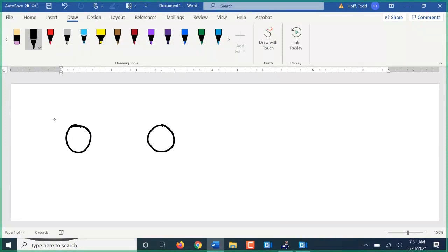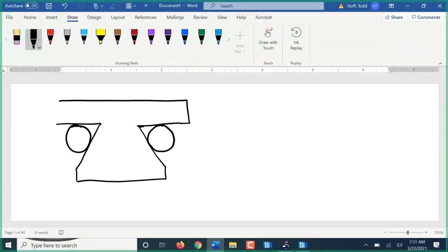So the last example we did yesterday was two pieces of round stock inside opposing V's. Here we're going to have two pieces of round stock on V's that are facing away from each other. Let's give these angles here, we're going to call them each 54 degrees, 30 minutes.